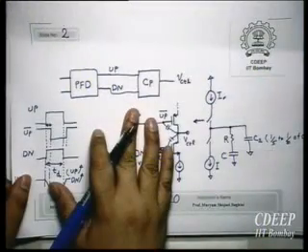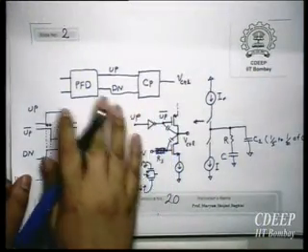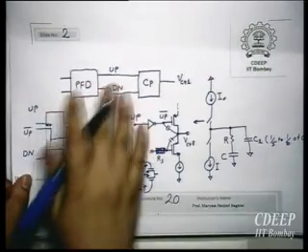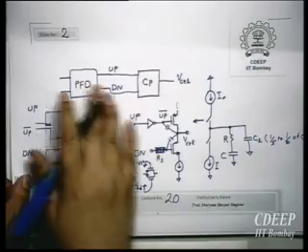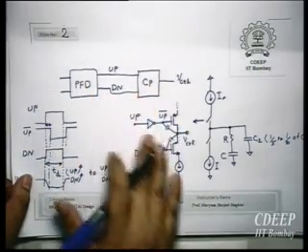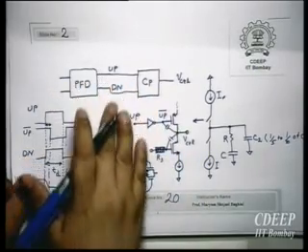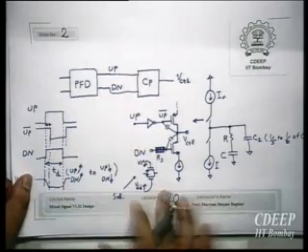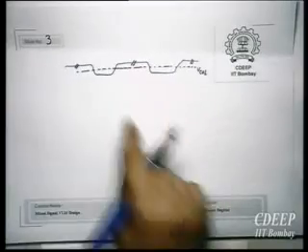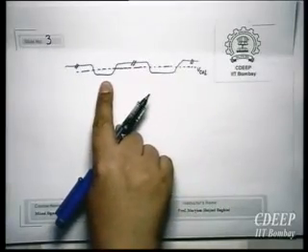For example, the way you can model it, you consider you have an ideal charge pump and an ideal phase frequency detector, meaning that the delay from the output of the phase frequency detector to the charge pump output is the same for the up and down paths. But then this appears as a step disturbance at the input, right?